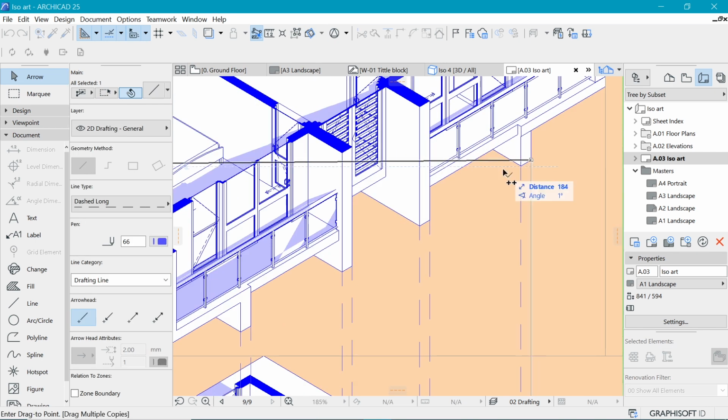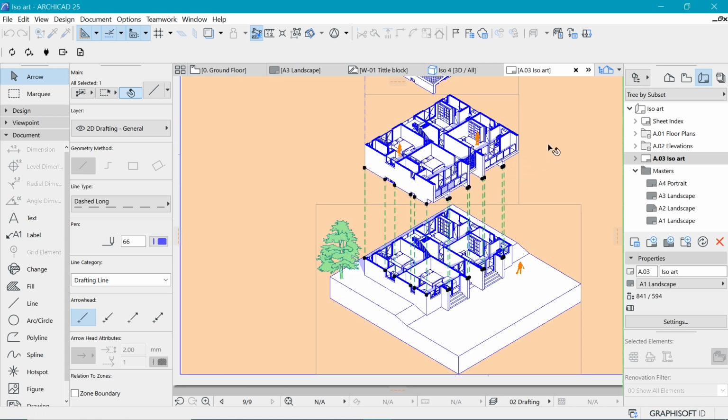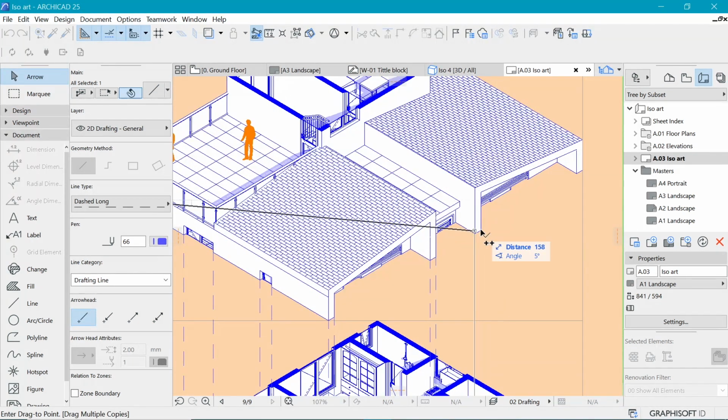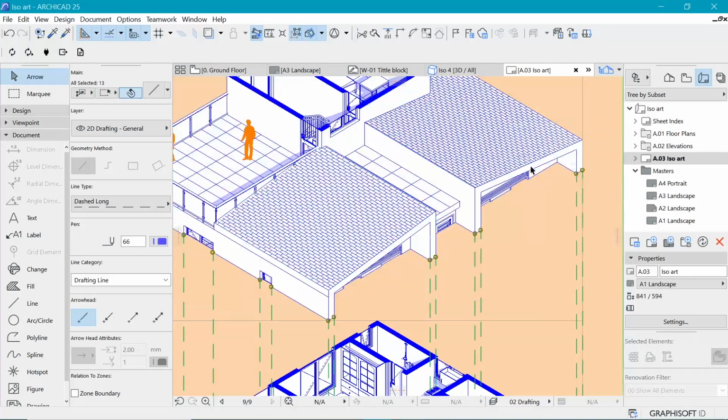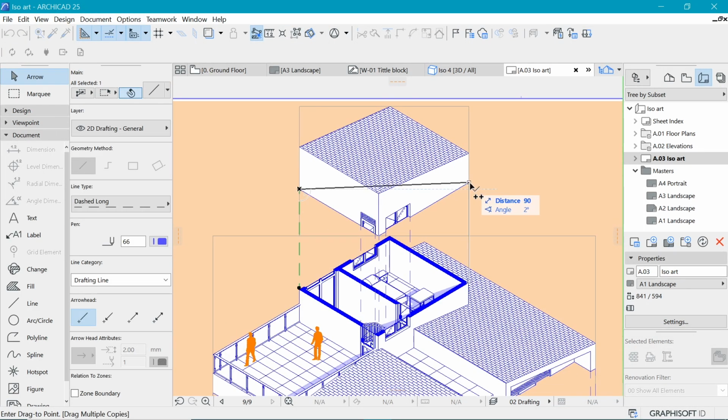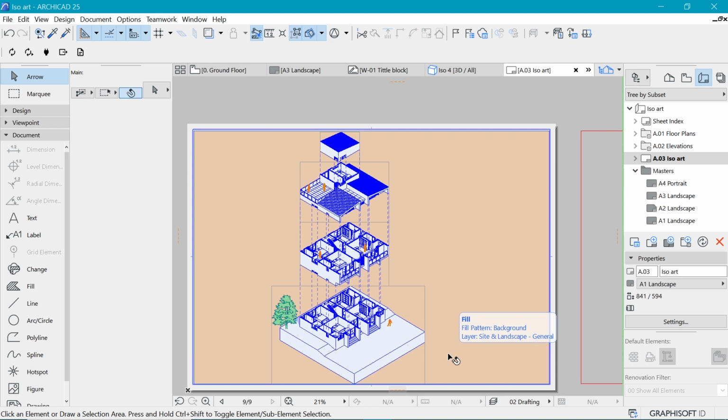And now next to that is duplicating those lines across the entire drawing for the ground floor, first floor, and the roof. So once we have those beautiful lines, we want to actually give some information about this drawing, which is the final part. Now, in the previous videos, we did it manually, but this time we want to use zones, and that is the advantage of using zones, so they can list the spaces out for you automatically.